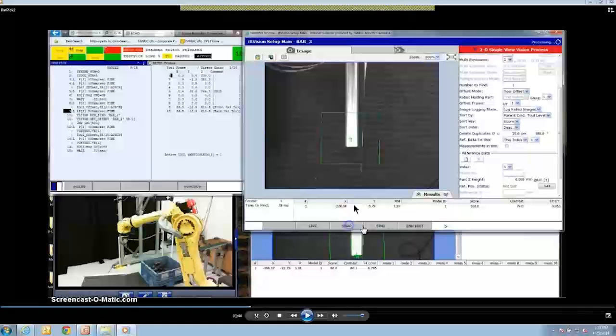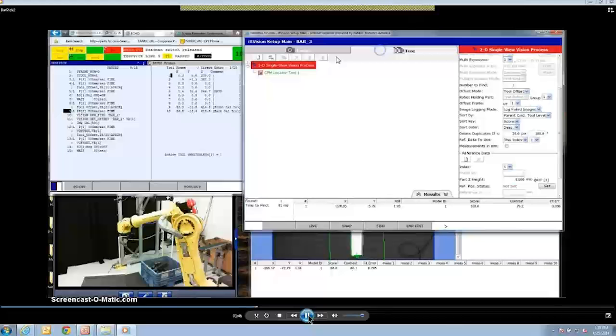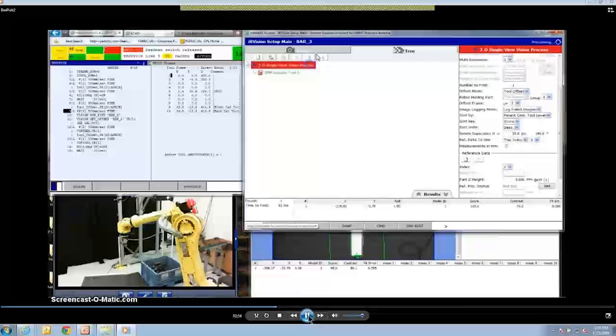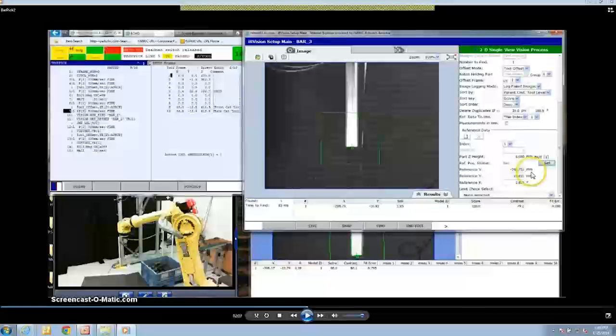So we snap and find. You can see here, again, everything's relative to the tool frame. So our origin of our locator is like 278, which is about 300 millimeters from the center, which is right. Now I'm going to just, for no good reason at all, change the origin, just to illustrate how the positional information is always relative to the origin. Now we're using nominal positions and reference positions, so where the origin is doesn't really matter. It's arbitrary. If you change it, you need to reset your reference. But you can see here that it jumped about 20 millimeters as I move my origin from here to here. But where the origin is doesn't really matter when you're doing reference positions or offset motions. If you want to use found position for some stuff, which you do, which is a whole other topic, then where the origin is does matter.